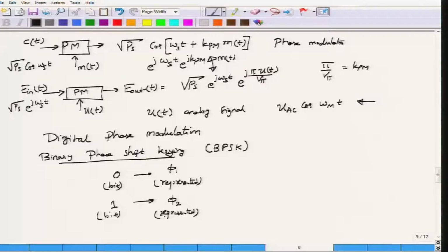How can I do that in terms of the optical phase modulator? Well, what is the phase that you want? Let us suppose that phi 1 happens to be equal to 0 and phi 2 must be equal to pi. These are two widely separated phases. So, it would be natural to assume that you can map 0 bit to 0 phase and 1 bit to pi, or you can turn it around, it does not really matter, whichever you take is up to you. The convention you can follow with either 0 being pi and 1 being 0. Okay. So, let us try with this constellation, later we can switch it if we think that this is not a very nice representation.